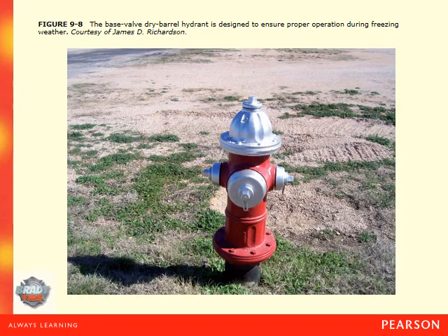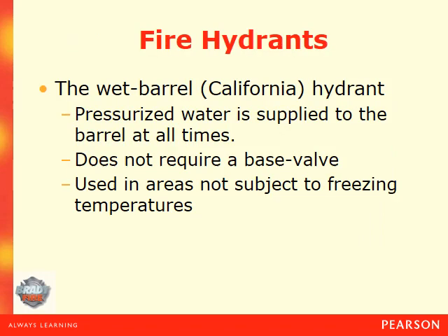Here's a picture of a typical base valve dry barrel hydrant. The other type of hydrant is the wet barrel hydrant, and this has pressurized water in it at all times. It does not require a base valve because this area that they're in is not subject to freezing temperatures. Something that's what they call it California, so Florida, basically areas that don't freeze.